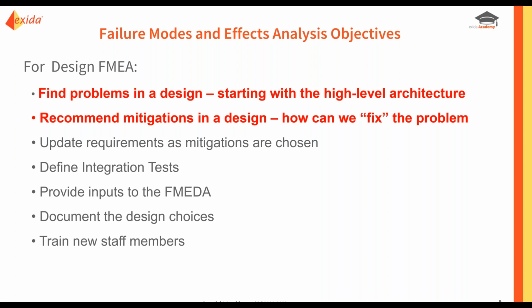And there's a few more. We want to update requirements as new mitigations are chosen. It's an ideal time to define integration tests, sometimes to show that a particular failure mode is impossible or at least unlikely. Provide inputs to a failure mode effect and diagnostic analysis if you want the quantitative failure rate and useful life predictions.